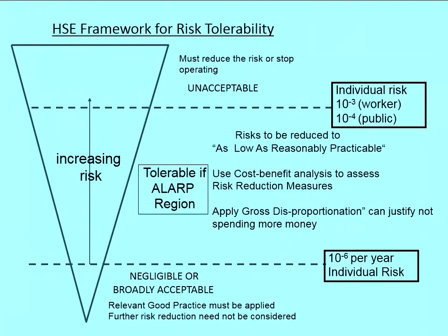That means you're complying with codes. And then what it goes on to say, the zone between the minimum and maximum risk has got to be evaluated. But this is the important thing. The demonstration of ALARP starts with confirming good practice is being applied, and good practice means following pipeline codes and standards.